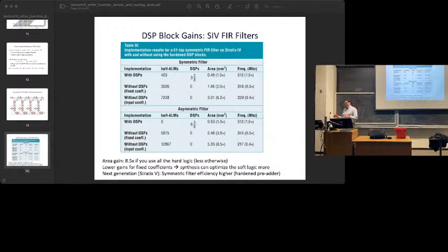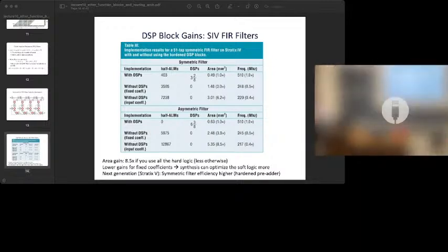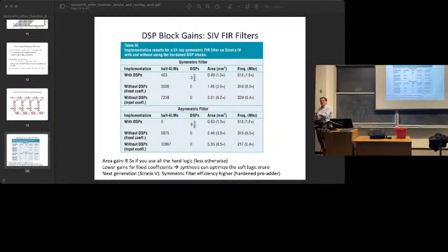So they're in the ballpark, 4x to 8x, but notice they're not at like 20x. So it is difficult to get once you basically put a bit of configurability into a hard block, like a DSP, and you account for the fact that applications never use everything, you don't get to those 20x and 30x improvements that we saw earlier, where people said if you took logic and you just put it into gates, how much more dense is it?